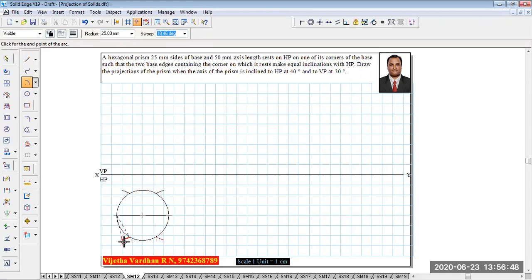Now, the moment you draw an arc like this, you get the 6 different corners. Using your HB pencil, starting from any of the 6 corners, start joining all the lines, whose length will always be equal to 25 millimeter. This is how one has to draw the construction of a hexagon. Once the hexagon construction is finished, using your pencil and scale, start giving the annotations like AA1, BB1, CC1, DD1, EE1, FF1, and to get the axis position, use the 2H pencil.